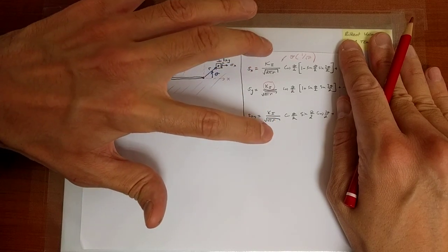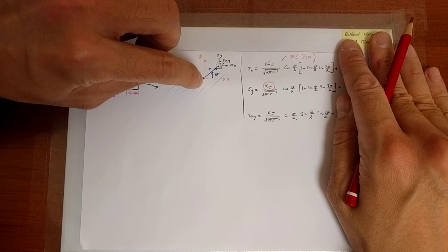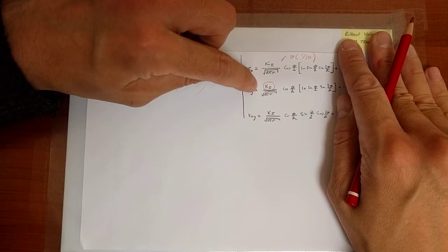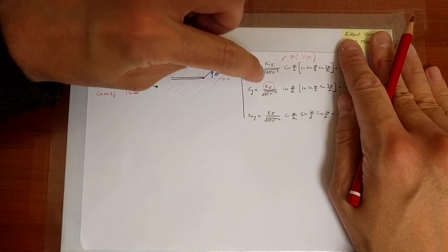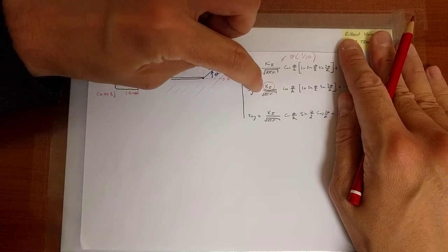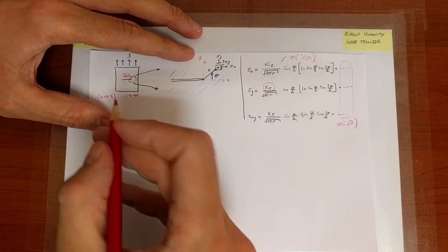These are the terms that dominate the stress field within the zone close to the tip of the crack. And these stress components are ultimately responsible for what we are going to call fracture. Within those components, there appears this factor K1. Now, what is that factor?